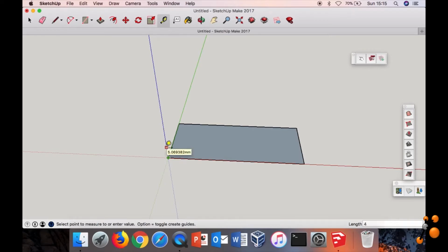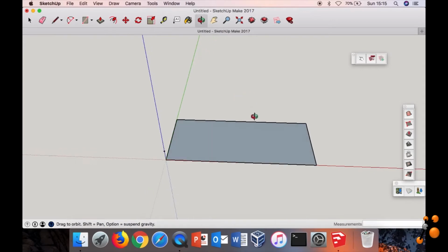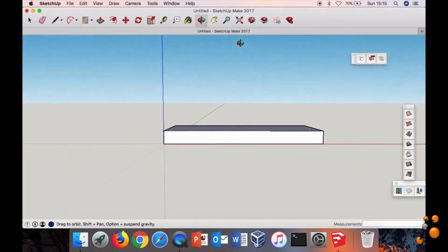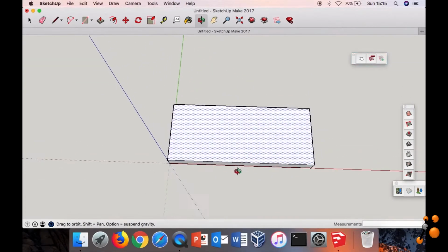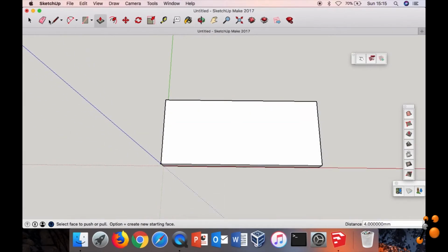So here 4, so we put some dot here, and we extrude this until here. Okay, so we have already this bottom part like this. So now I'm going to put some line to define, for example, the wall. Here it's 4 millimeter. Here we have 4 millimeter, again here 4 millimeter wall.